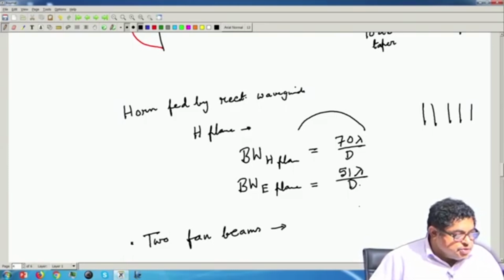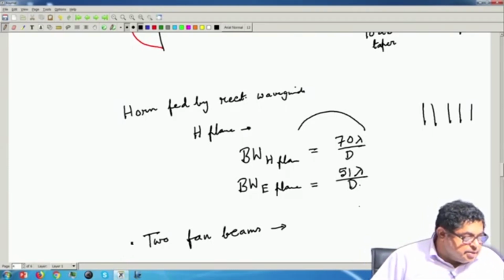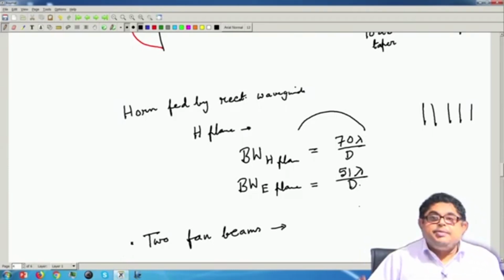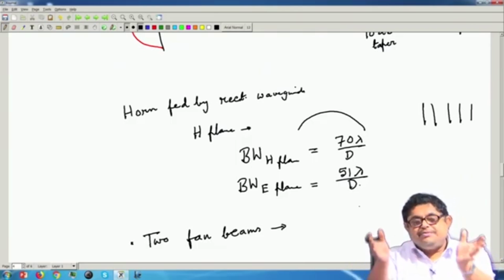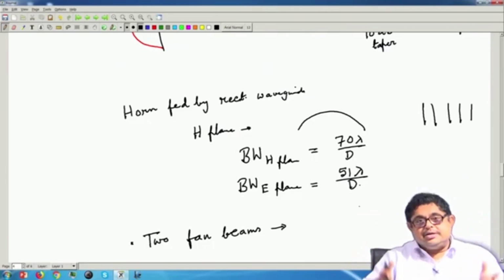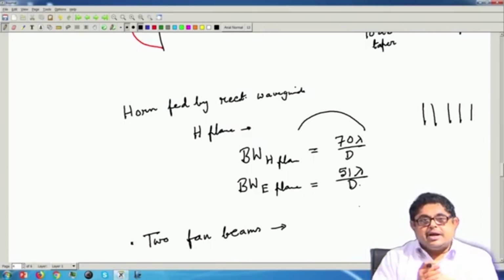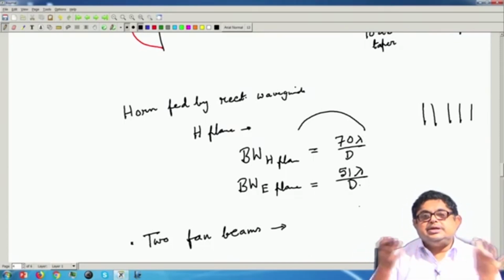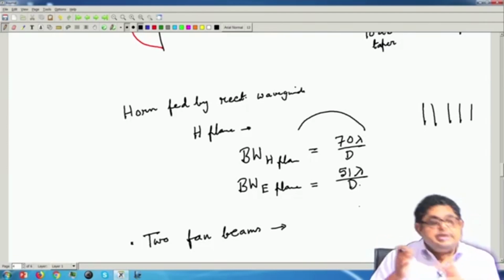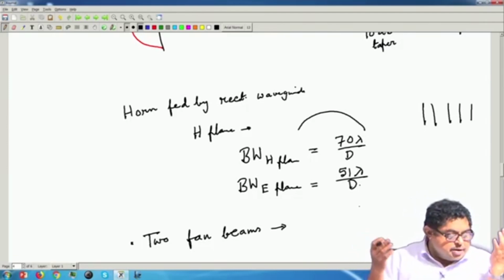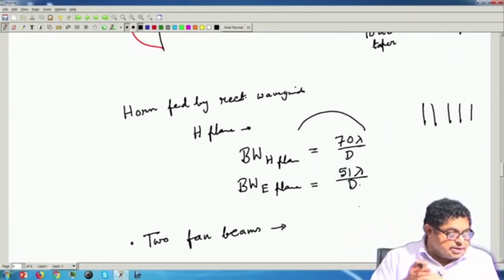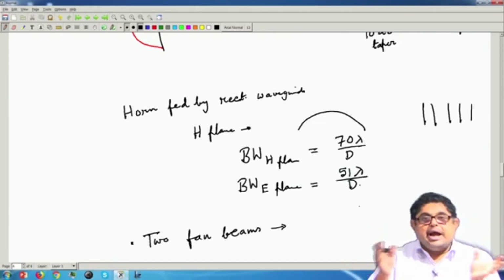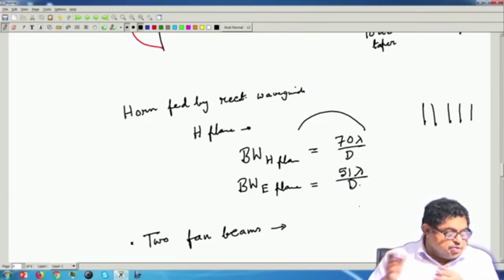So, in the case of planes, first a narrow azimuthal fan beam is rotated through 360 degrees at most, or if you know from which sector the threats or aircraft are coming, then some lesser angle instead of 360 will suffice. Then a second fan beam, narrow in elevation, moves up and down until a target is detected at the same range as the previously acquired echo.